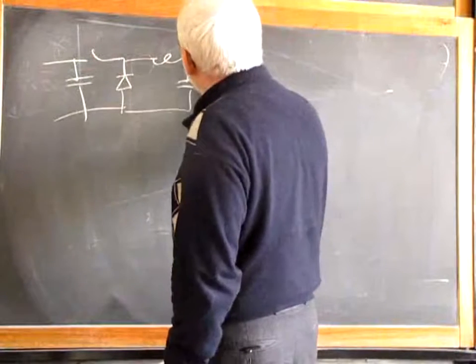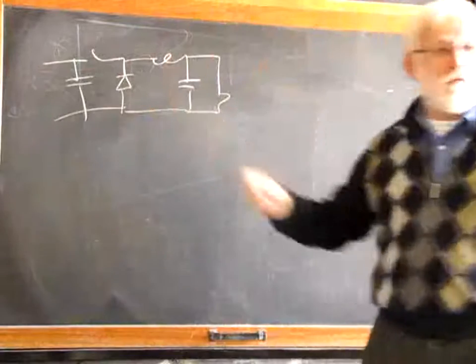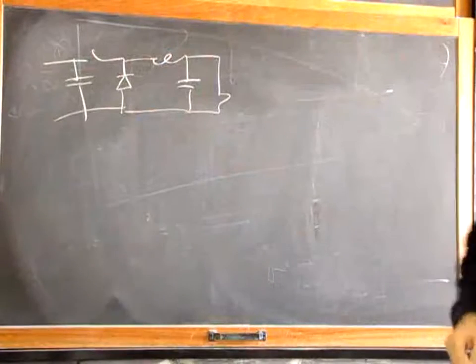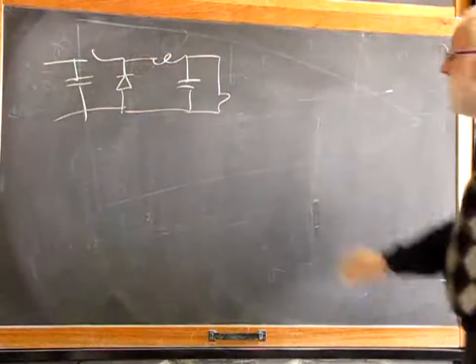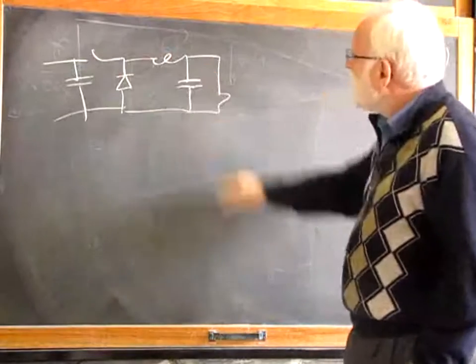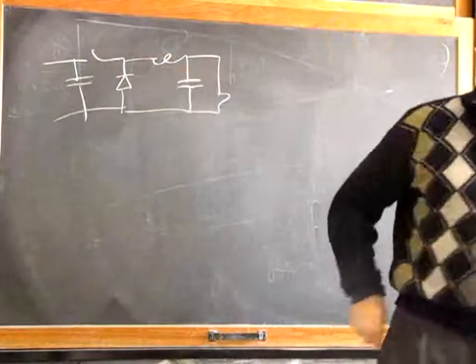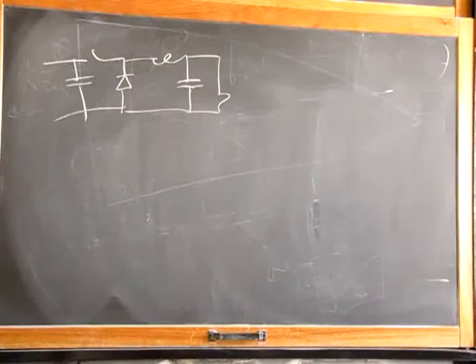that has these specs. I need the specs to put numbers in my transfer function. How much is the inductor value for the buck converter in the lab? 220 microhenries.